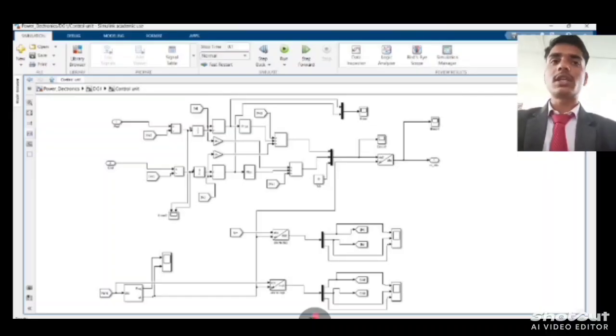Second is the control logic or PI controller, where the middle part includes gain, summation and integrator blocks, which give us the output. Together they form a proportional integral controller. The proportional path reacts instantly to error. Then the integral path accumulates past errors to eliminate steady state offset. So the output from this controller generates a control signal.